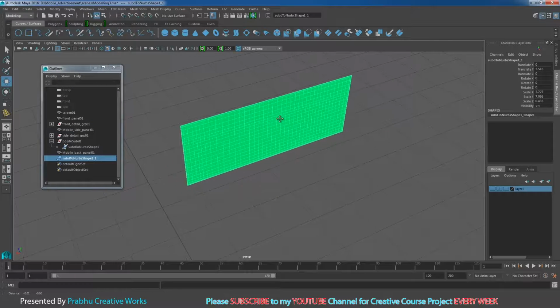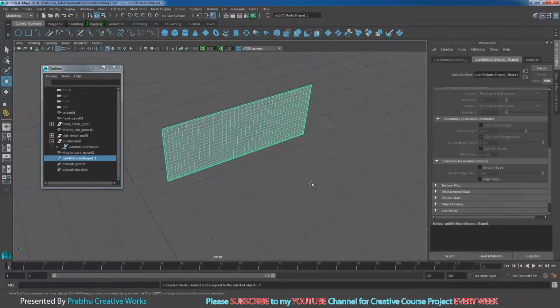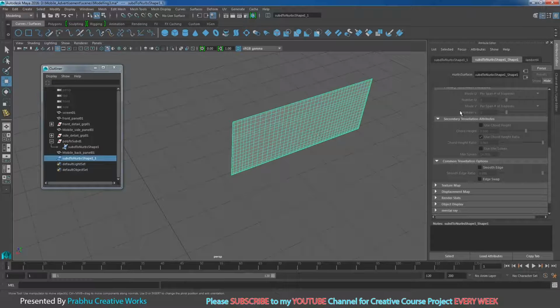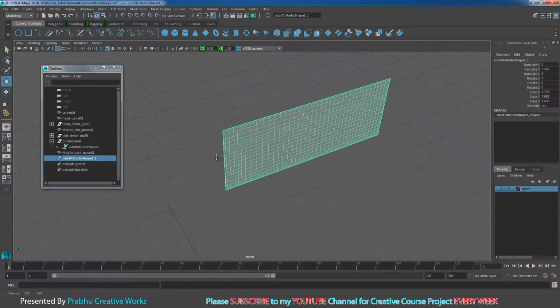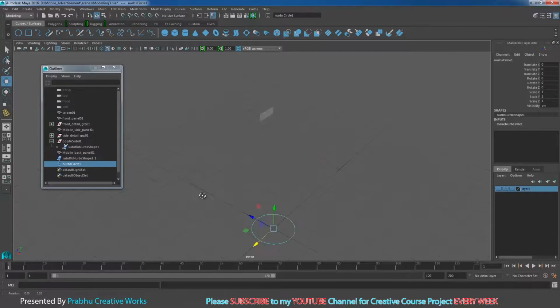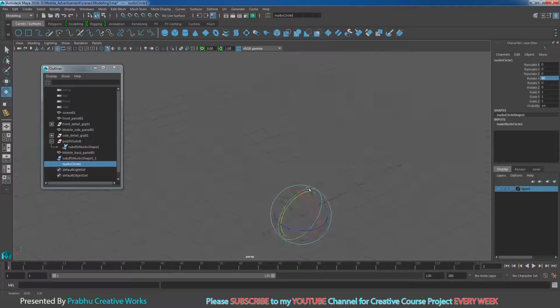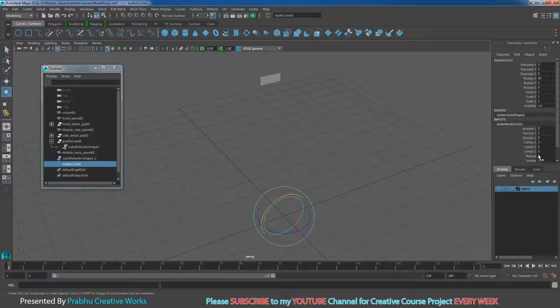So now we want to apply, right click and choose assign new material and choose Lambert. So it will be clean. So I will close my attribute editor. So now click on this NURBS circle, so it will be automatically created in the center of the grid. Press E, you want to rotate Z in 90, rotate X in 90, so like this. So go to nurbs circle, inputs, you want to set sections to 20.